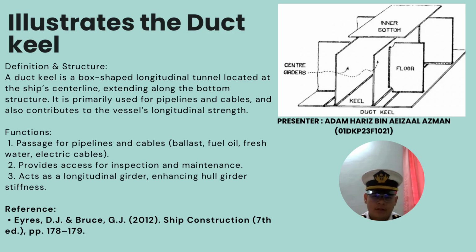Second, provide access for inspection and maintenance. Crew can access pipelines for maintenance, repairs, and leak detection, and it is essential for survey and safety checks. And lastly, act as a longitudinal girder, enhancing hull girder stiffness. It acts as a center longitudinal girder, contributing to the overall hull girder and helps the vessel resist hogging and sagging stress.